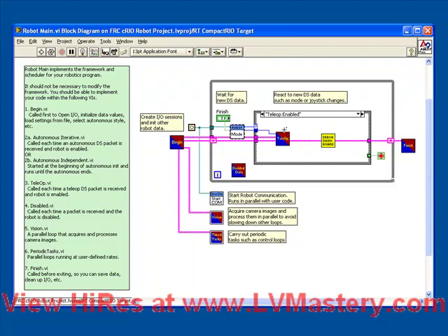The end result of this whole thing is that it's not good to have time-critical information be handled in your Tele-Op case. And that's why there's a VI here called time tasks, which runs completely in parallel to the loop which contains the Tele-Op. All of your time-critical periodic functions, such as control loops, should be monitored externally to the Tele-Op.